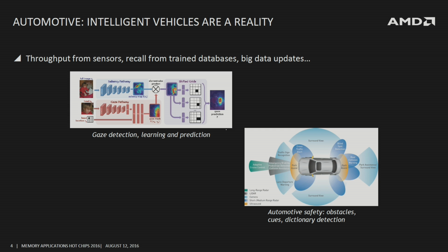But what these guys are figuring out is that we need to see things from the car in every direction, both in the XY space as well as the Z space. And what's happening now is that there are so many sensors being put into the car that the data coming in is becoming one of the bottlenecks. Right now, the rule of thumb is that they're going to have at least 10 cameras per car in the visible spectrum, at least 5 in the LiDAR spectrum, and 5 more in some other modality. The amount of data being generated out of that is so high that there's a separate processor just to do the fusion, much less any of the machine intelligence.